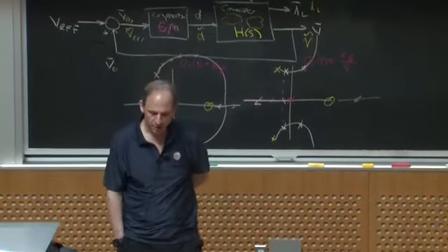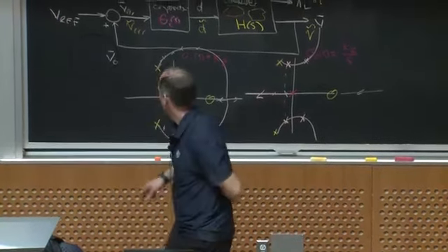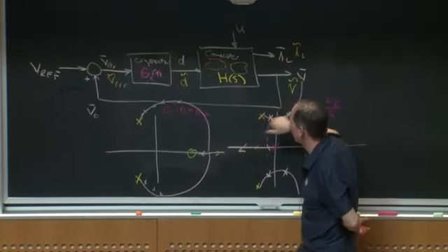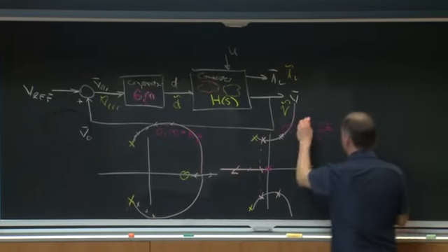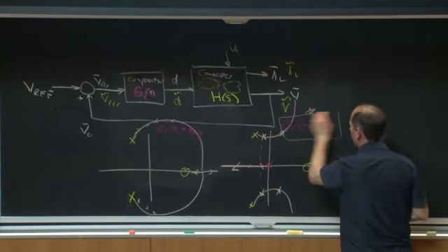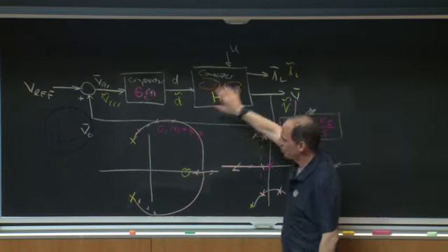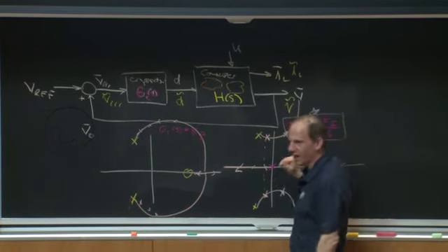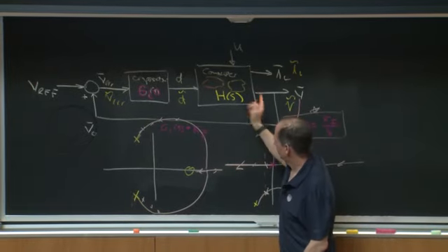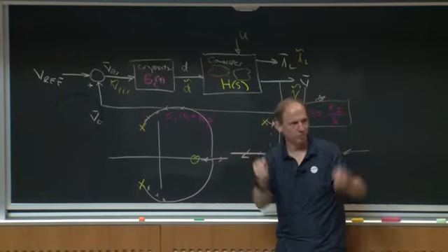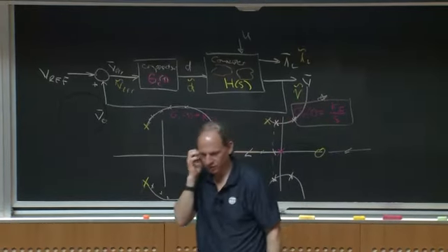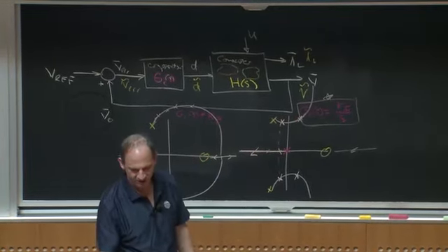What I'm going to do is let me put this system in a closed loop. I'm going to use a compensator. I'm going to use an integral controller. Okay? And I'm going to use my plant dynamics there. And then for different values of Ki, I'm going to take the closed loop, find the closed loop pole locations, and then I'm just going to plot them. Okay? And I'm just going to do that, physically in MATLAB.